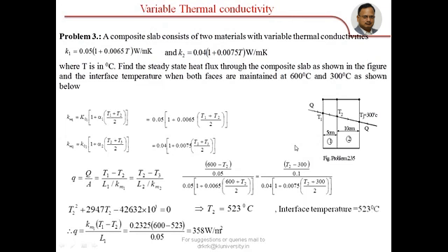So in any problem, if thermal conductivity is given as a function of temperature, don't take it as an independent parameter, treat it as a variable with respect to temperature and then keep it within the integration, and after substituting K as a function of temperature, you proceed for integration and do it.